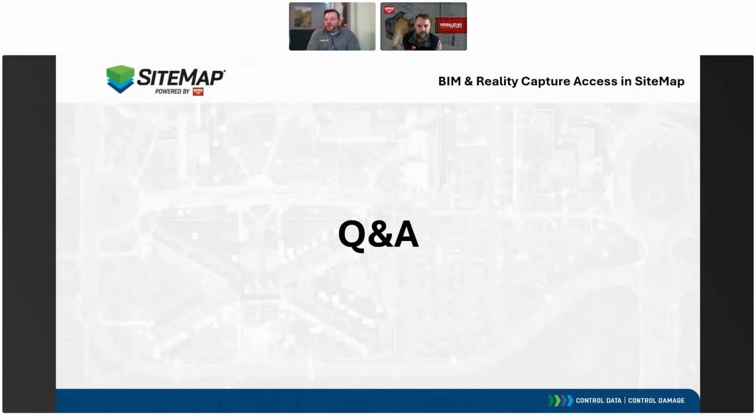We weren't just focused on a few points around the area we're working. Because we're using laser scanning, we're capturing really everything that's in view within hundreds of feet, and we're able to do these checks even though that wasn't our main focus. It became apparent when we overlaid that as-built on top of our model. Just think of laser scanning as really a photo. Anything in view of the laser is going to add value to that model. It's pretty incredible, and it's easy. We just have to be incorporated in the process, and we can provide these solutions pretty easily.